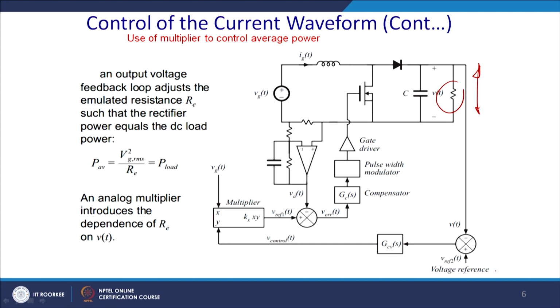By scaling down you get a voltage reference. Thereafter it has been multiplied by a scaling factor, or filtered by a filter to suppress the high frequency noises or the ripple, and ultimately this voltage will be fed to this multiplier. In the same way, this is the rippled DC, that is basically VG at this point.